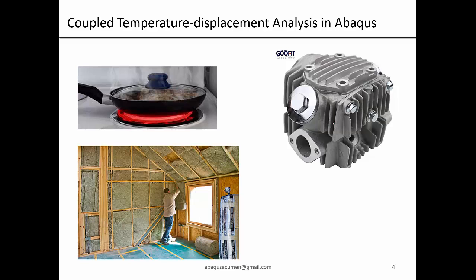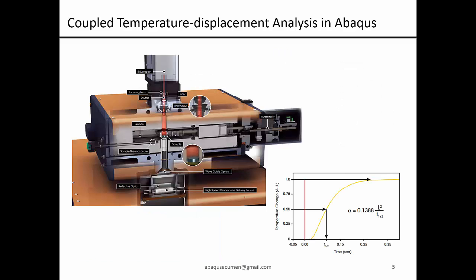Something like a two-wheeler engine, you see a lot of fins because you want to get heat out. Once heat is getting out, the temperature doesn't rise within the engine cylinder, because with high temperature your metal properties degrade and you may get thermal shock and cracking. So you require high dissipation. In the case of a house, you want good insulation, so you want a low thermal diffusivity.